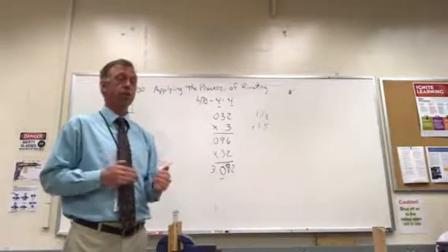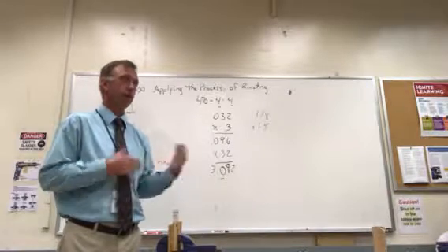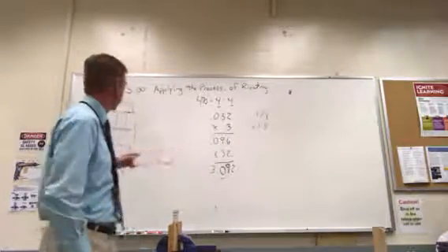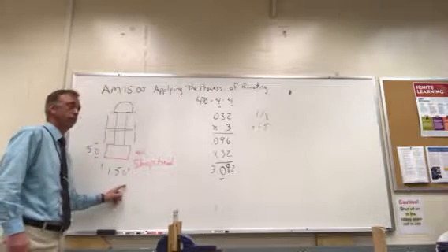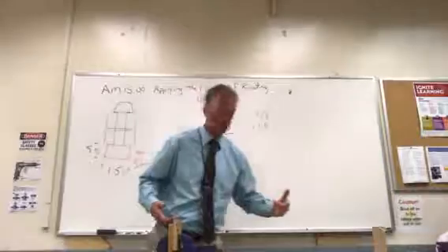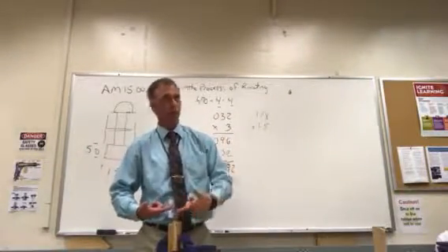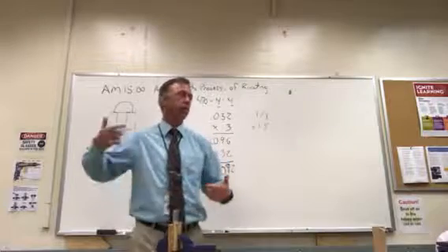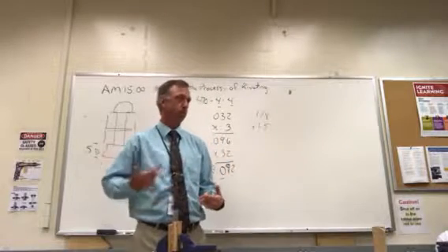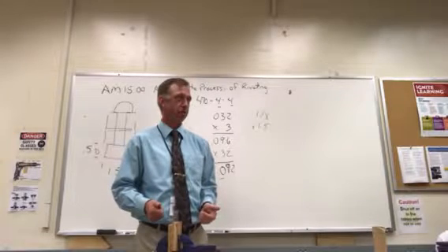And then what do we do with the length? You add the two thicknesses together. Good, we add all the materials and then 1.5D. Wonderful. So then in the process of riveting, we're going to make sure that everything is level, everything is even. We're not going to tip it up, and then we're just going to pop it, and that's going to be it. Good? Any questions about that?